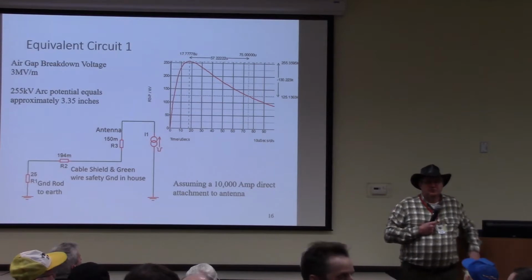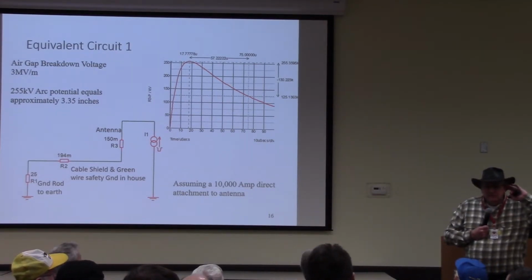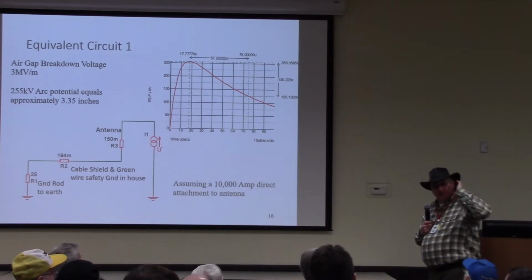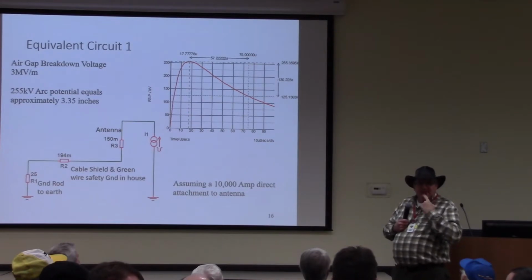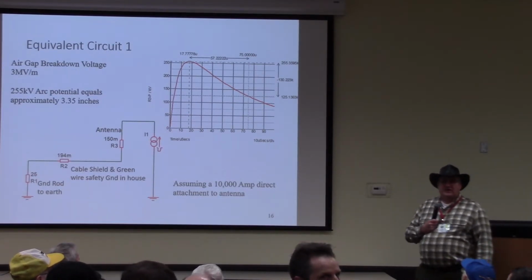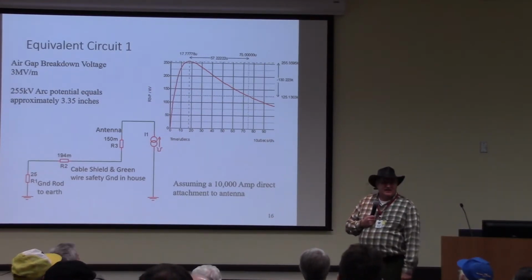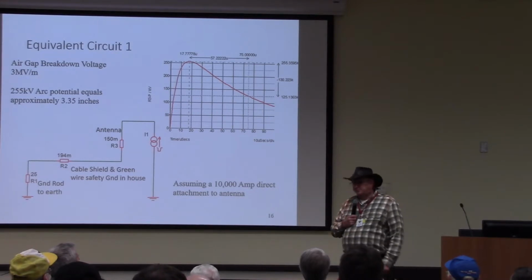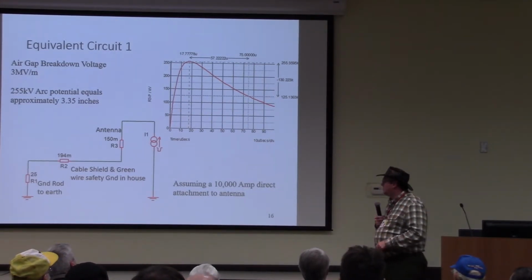They have to do 2 rods now if they don't measure. That's just the latest National Electrical Code. They just recently updated it, and I'm not up to date on that. So let's say it is 2 rods. We'll get into what that does for you in just a few minutes.